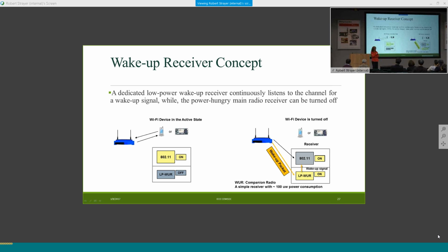And one way to enable low power, especially on downlink, is that the very easy way of doing low power is to have limited transmit power on uplink. So the range is limited. The best way is to have a mesh network, right? So extend it. What I'm trying to say is that if there is a mesh, the wake-up receiver can still be a companion to that. It's transparent to the wake-up receiver operation. But today's Wi-Fi doesn't have mesh, or 11s is not deployed.